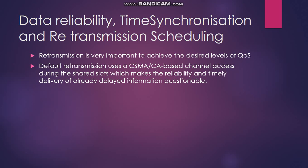In this aspect, 802.15.4e can serve as an excellent example as it offers interference-free channel access. It also implements time synchronized channel hopping, TSCH, for better reliability. However, the desired packet reception rate, PRR, could be challenging to achieve due to some significant interference sources native to the industrial environment, when ensuring a quality of service.